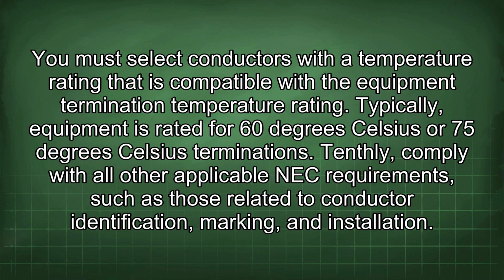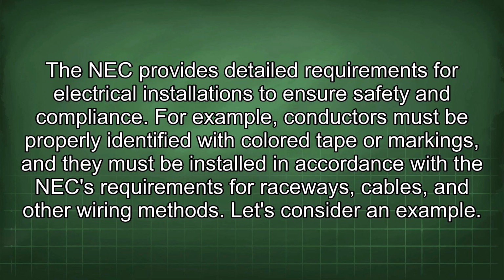Tenthly, comply with all other applicable NEC requirements, such as those related to conductor identification, marking, and installation. The NEC provides detailed requirements for electrical installations to ensure safety and compliance. For example, conductors must be properly identified with colored tape or markings, and they must be installed in accordance with the NEC requirements for raceways, cables, and other wiring methods.